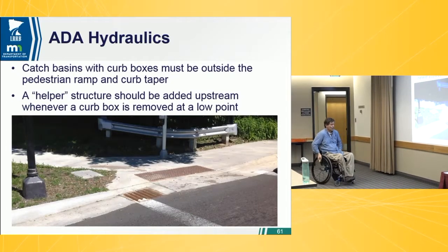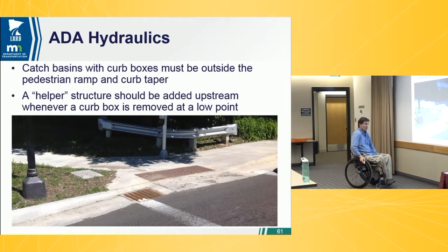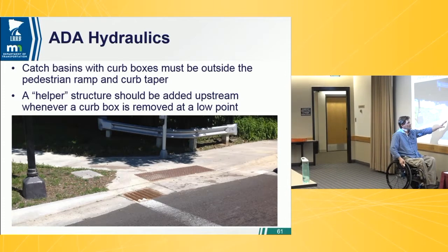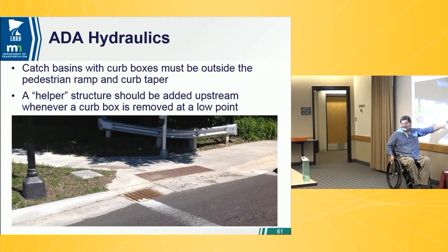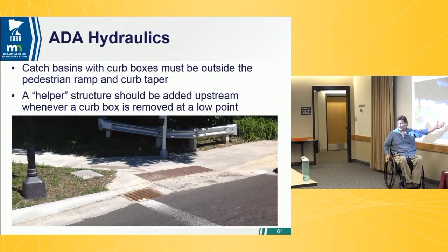I'd like to talk about this one. This one probably should have been an ADA safe grate too. We say if it's within a foot, generally we should. This one's in a sump. It's kind of an ankle breaker, so not a good deal there. So we don't want to do that. Even bikes could take this flare and come through here and still get in those vane grates.